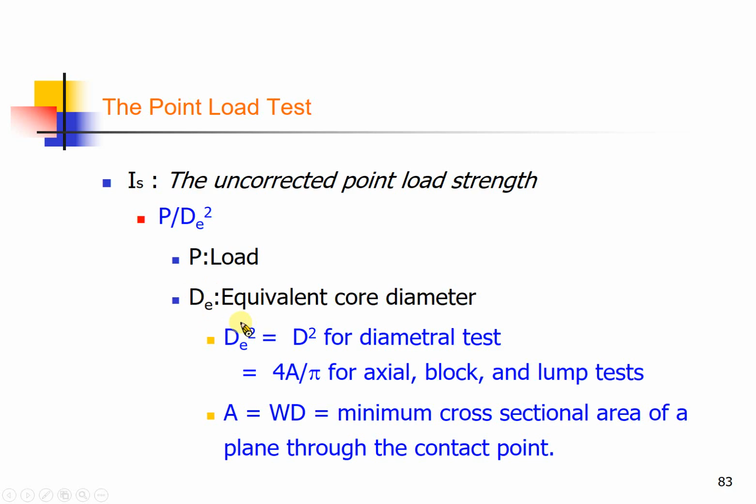Then you can take the rock specimen and do the point load test directly. You don't need to cut the specimen and care about the ratio between height and diameter, and the polishing so the ends are parallel to each other. A lot of things to consider, right?